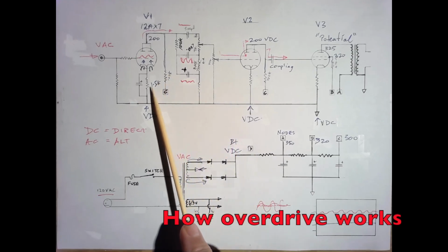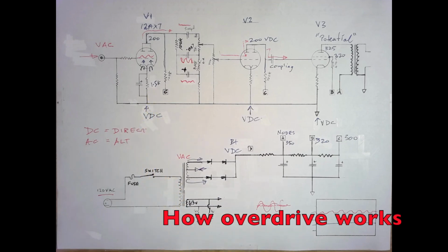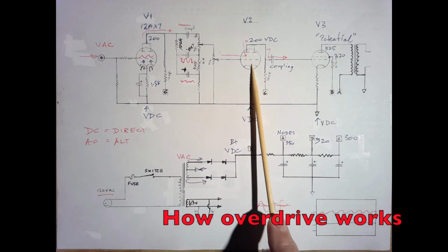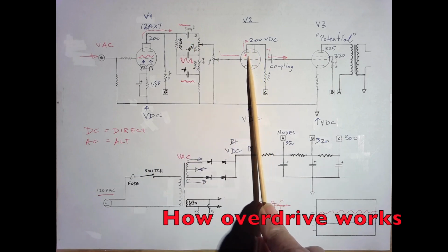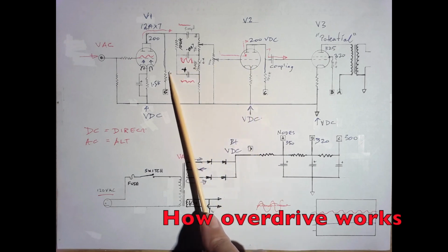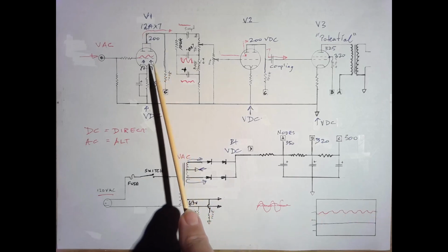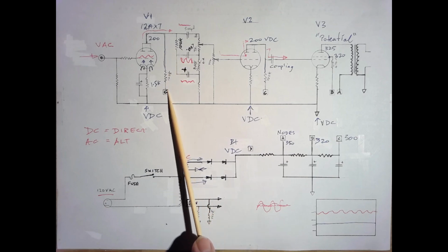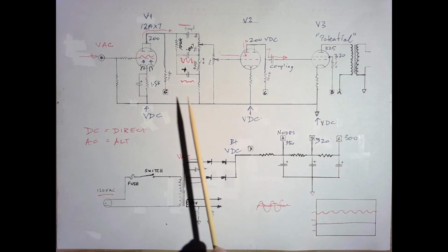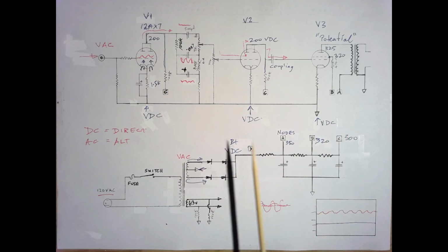We have a load resistor and a cathode resistor, and these determine how the tube will behave when the AC signal is injected into it. Also of interest is that when we bias a preamp tube to be hot in order to create breakup, we're actually sending increased current to the next stage, which overloads the next stage. We can have a smaller plate resistor, which would actually allow a higher voltage potential here, but in fact that will allow more signal to escape past it and drain out to ground, and it will literally come this direction and drain out to ground.